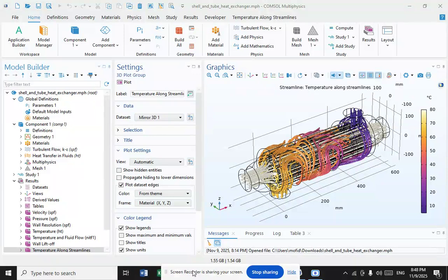And what about the dynamic scraped surface? Another type of heat exchanger is called the dynamic scraped surface heat exchanger. This is mainly used for heating or cooling with high viscosity products, crystallization processes, evaporation, and high cooling applications. Long running times are achieved due to continuous scraping of the surface, thus avoiding fouling and achieving a sustainable heat transfer rate during the process.